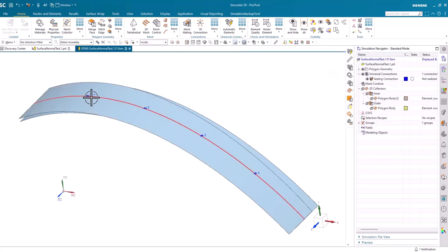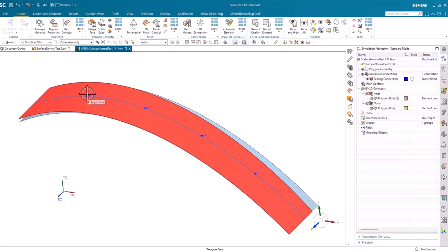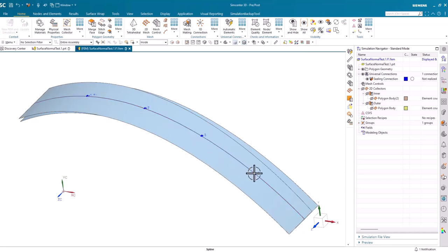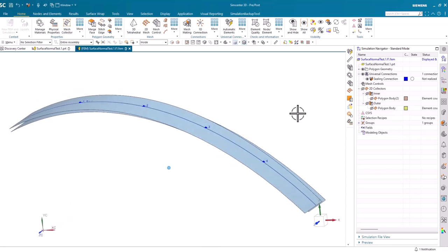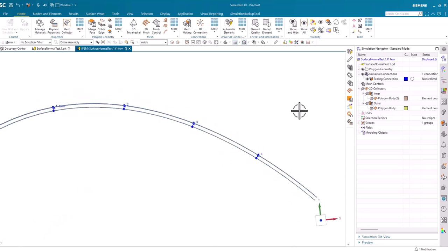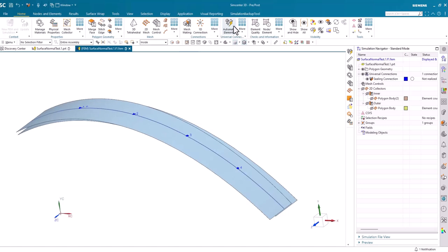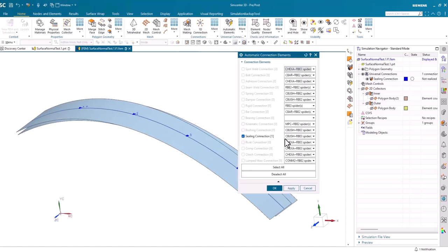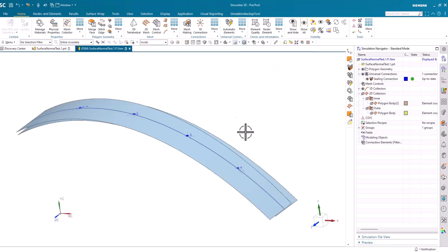So now I have a ceiling connection at point 1, 2, 3, and 4. Should end up with 4 spring elements and 8 spider elements. So now I'm going to generate the connection using C bushes and RBE 3s. So I say OK here.